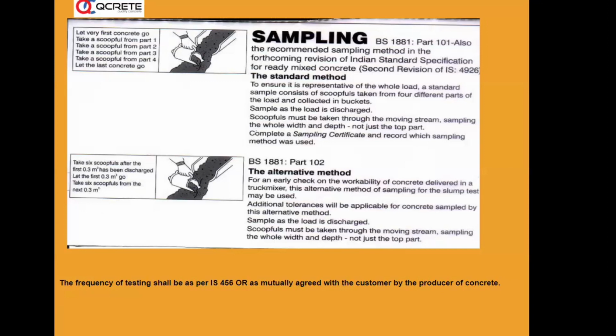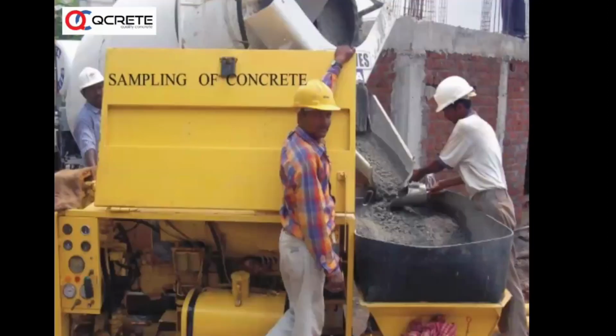What you are doing with the concrete once the concrete is produced, how you are taking the sample. So this is an example here. The concrete is falling from the truck like this, and the scoop has to move like this in a vertical, means that perpendicular to the movement of the concrete flow. So this has to be done like this actually.